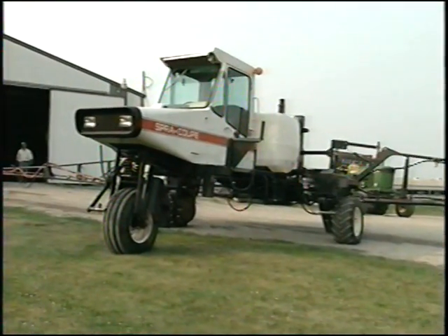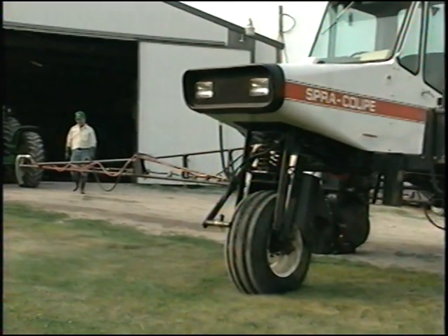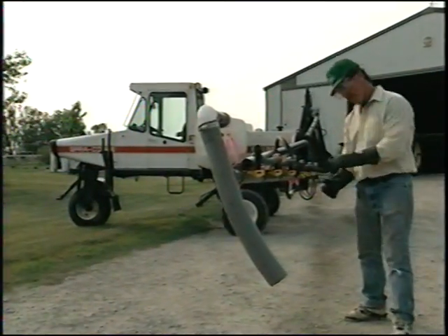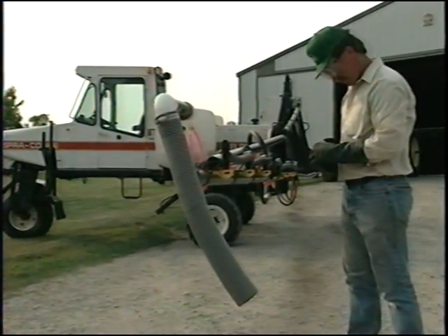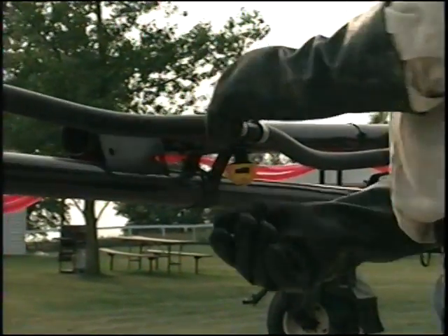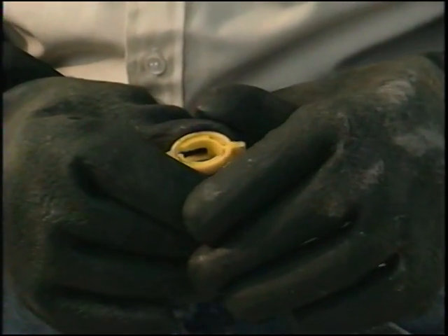No matter what type nozzle you choose for your application, and no matter how diligently you monitor spray pressure and volume, if the nozzle becomes worn or damaged, it will invariably produce an irregular spray pattern, greatly increasing the number of small spray droplets and leading to potential drift problems. As a result, nozzles should be thoroughly checked prior to every application.